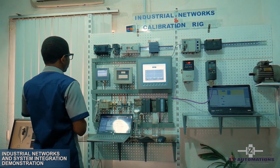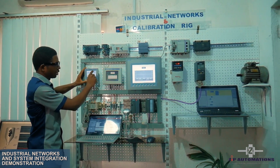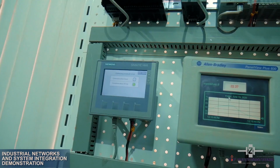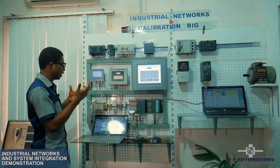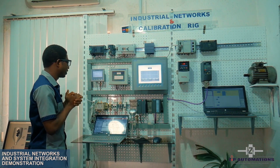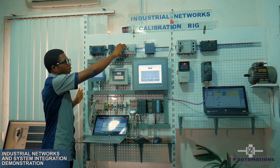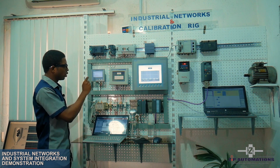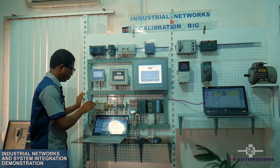In my KTP400 connected to the Schneider, I have a communication status screen. So this shows that communication is active because the devices are transmitting data over the network. Now I'm going to pull the cable to the Micrologix 1400. The communication status should change to communication error. So I'm going to do that right now.